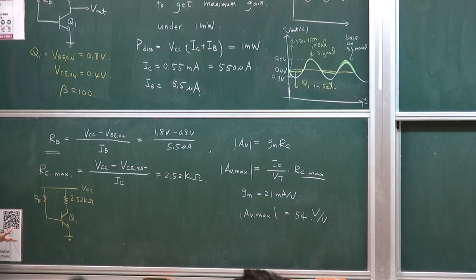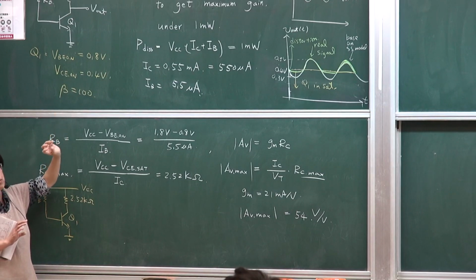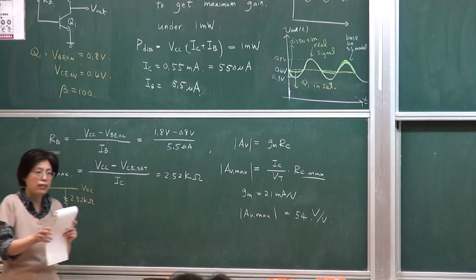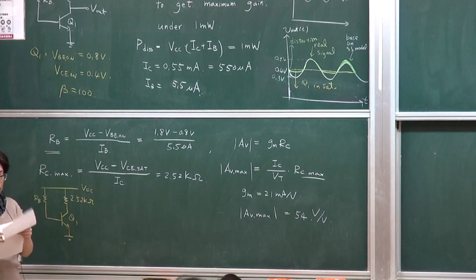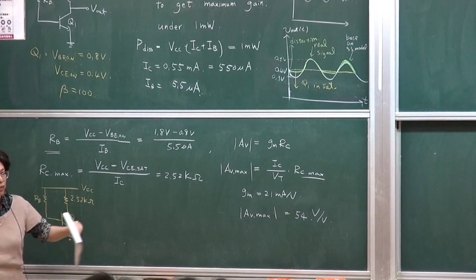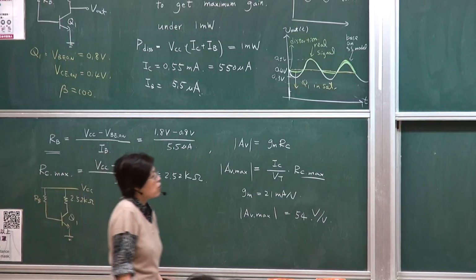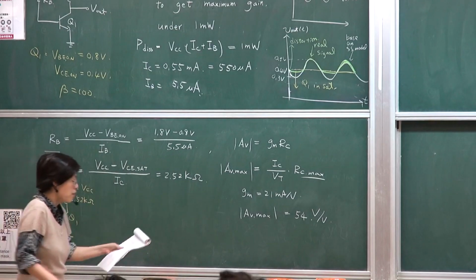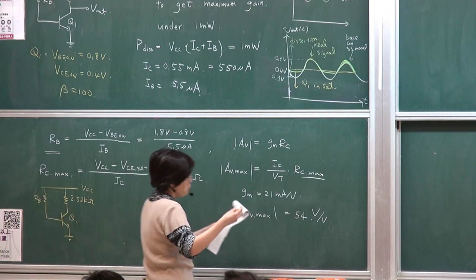So to prevent this from happening, finding the operating point is not typically limited by one specification, because if you're only looking at, for example, power and maximum gain, you actually didn't see other possible problems. So the more ideal way of finding a desirable operating point is to do a survey of the whole stage. So how does one do that? It's actually not that straightforward. I'm just going to use the same example.